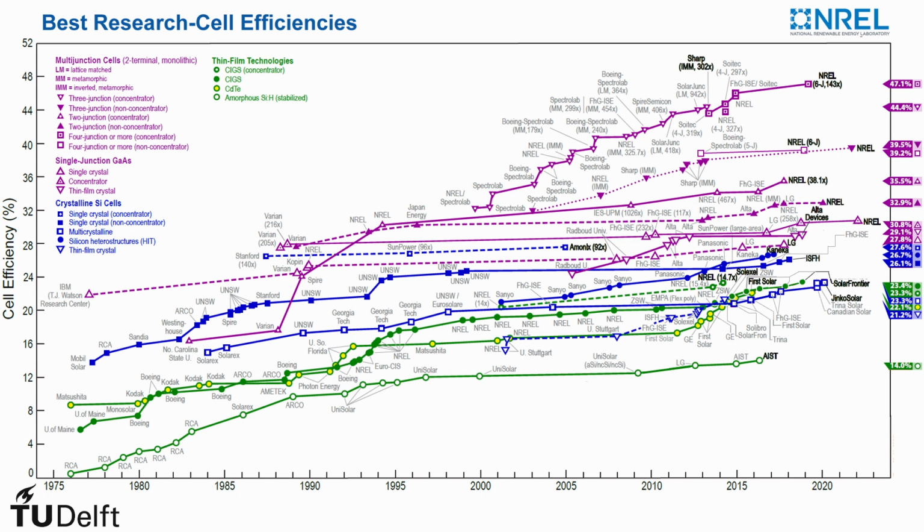In that time, organic solar cells have reached a record efficiency of 11.5% by Hong Kong UST, and UNIST has reached a record efficiency of 25.7% for a single junction perovskite solar cell. It should be noted that this is an initial conversion efficiency and not a stabilized efficiency, since no stable efficiencies for a period exceeding a few months have been reported for perovskites to date.